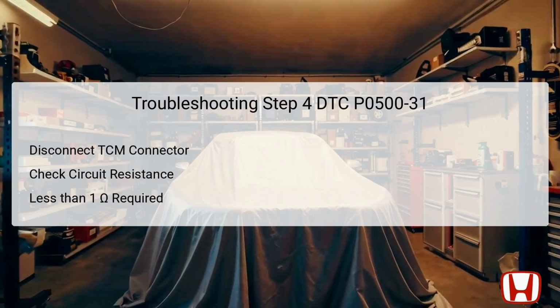If the resistance measured exceeds this limit, it suggests potential wiring issues, such as shorts or open circuits, that would need to be repaired or replaced. Troubleshooting the wiring is a vital part of ensuring proper sensor functionality. In this step, you will inspect the wiring for any visible signs of shorts or damage. Conduct a thorough check based on the service manual's guidelines for inspecting open circuits.